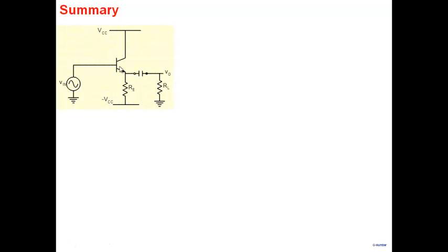So we have an amplifier like this. Everything starts with an existing solution and looking at it deeply as to what the problems with it are. And when we looked at it, we said one of the problems with a common collector as an output stage is that this particular stage draws power even when nothing is given to the load. And we said, let's look for a stage which perhaps does not have standby power.